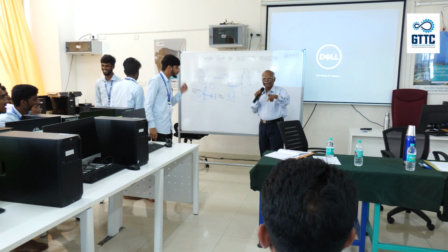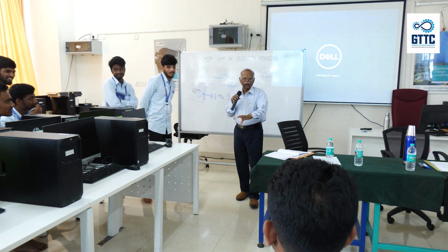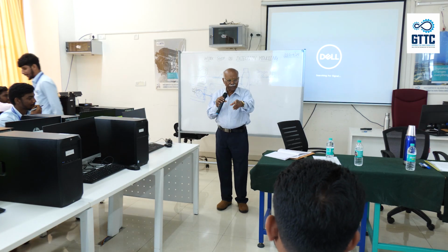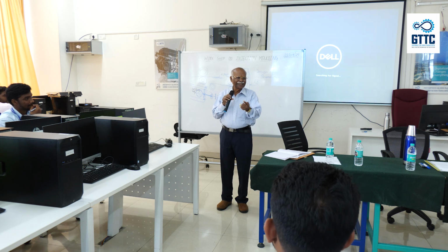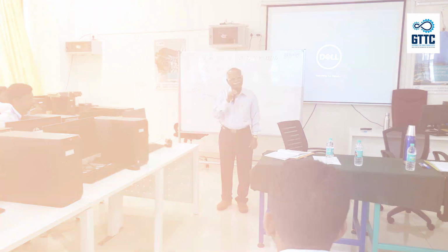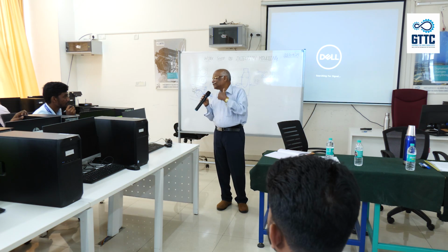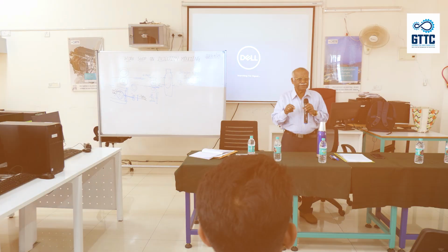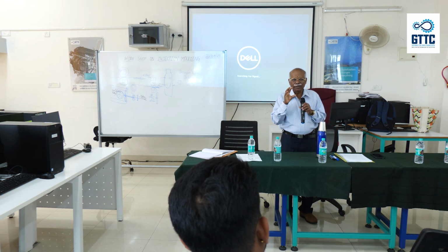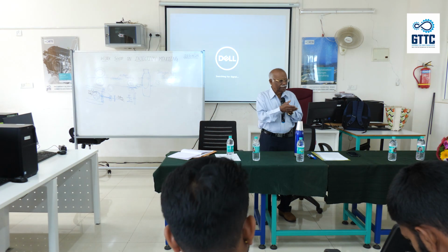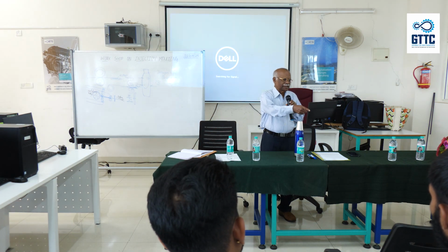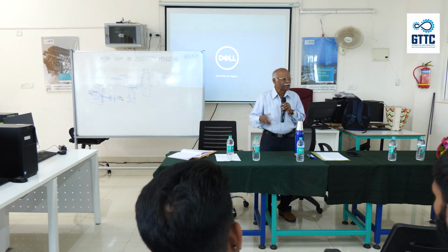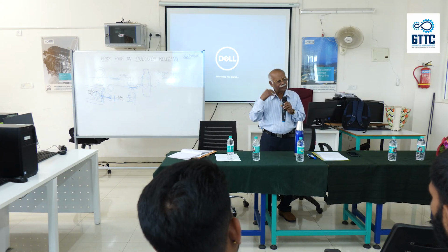Throw it. Now, what sound does it make? If it is a polystyrene, the moment you throw it, it breaks. The other will not break. That is one simple identification of your material. Somebody saying polystyrene means you don't know about the polystyrene quality. As a designer, you should be very, very aware in telling it. You know the difference? If it is a polystyrene, it will break at any moment. Why did I throw it? I know very well it won't break.